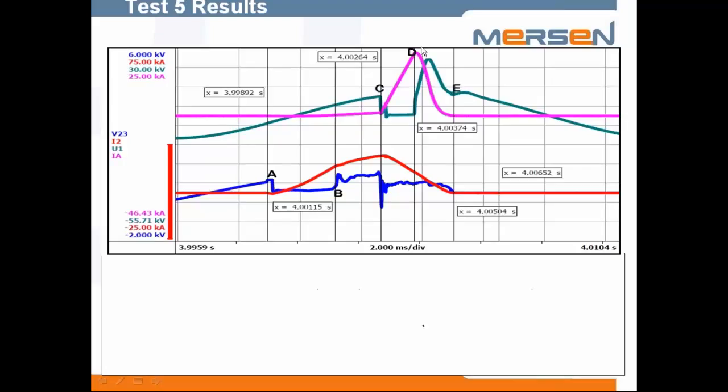What's shown on the top here is the medium voltage traces on one phase, and these are the low voltage traces on one phase. So if you look at the current at red, it starts at point A. And at this point, the current starts to rise rapidly, and the voltage falls to 0. That's because we have not yet melted the trigger wire. At point B, the trigger wire melts, and the arc begins, as evidenced both by the arcing voltage here at the flat top and the decreasing rise of the arcing current.